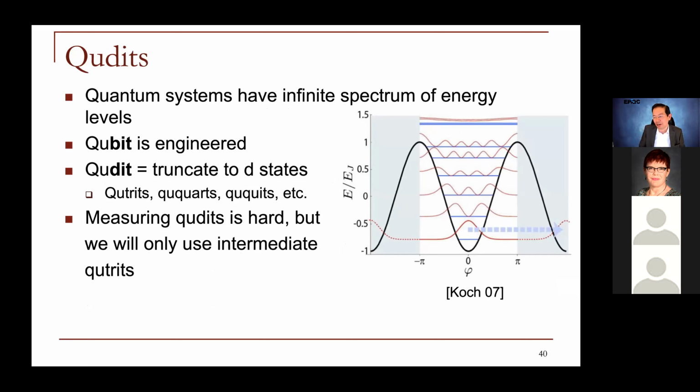So if you are representing a classical bit using voltage levels from say 0 volts to 5 volts, typically you break that into 2 pieces with a noise margin. But if you want to compute a trit or a 3-level bit, then you have to break that up into 3 pieces, and basically you have less signal and less noise margin, right? So you still have the same range.